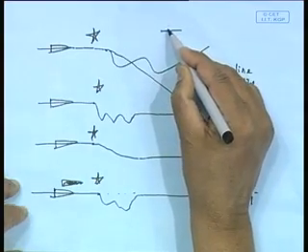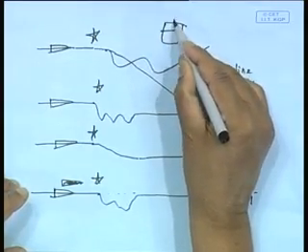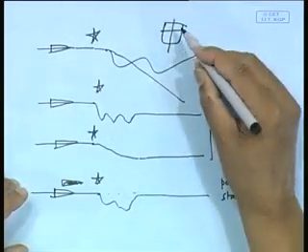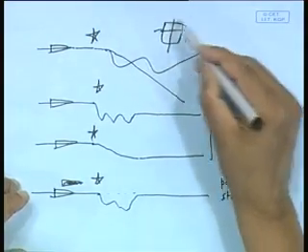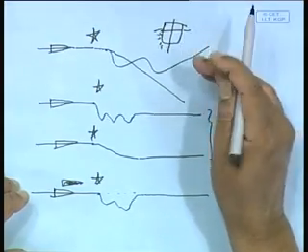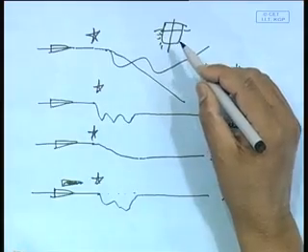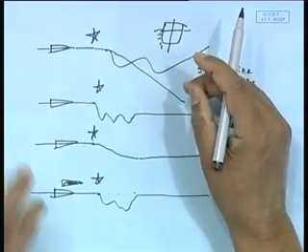You see, the difference is that in the static roll case, I have rolled the ship by a small angle. The moment I did that, the only force acting on the hull is what? Hydrostatic pressure. So what I essentially did was add up these hydrostatic pressures on the new wetted line to find the net moment acting on that hull. We called it hydrostatic only because the moment arose from hydrostatic pressure only.